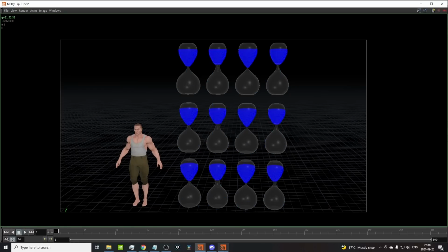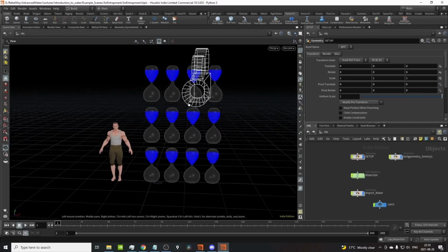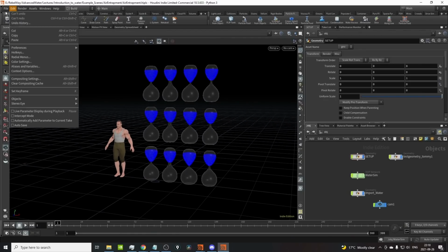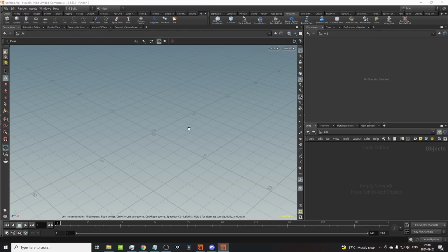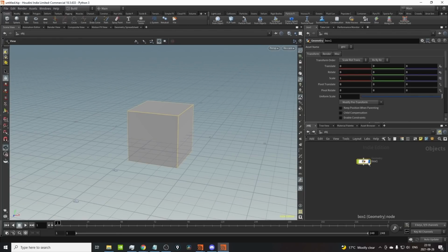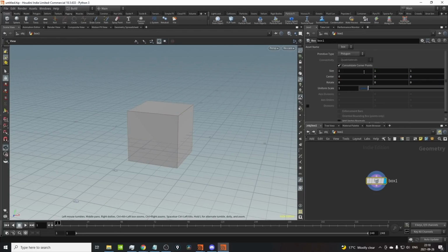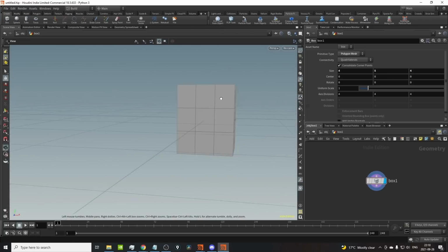So let's start out by going to Houdini. This is the scene where I simulated all of these things in. But let's just make a new scene. Start from scratch. Cool. So we'll make a container for our water to fall through, and we're just going to make a 5 meter tall box, and let's do a 4 meter wide, and this poly.